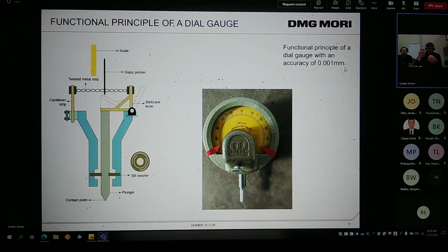Point measurement you can do also, but for point measurement a dial gauge will be better. You can do a point measurement also here, but you see that's not parallel, that's 90 degrees, and if you remember the movie, you can have a bad result, sometimes around 10 microns failure.